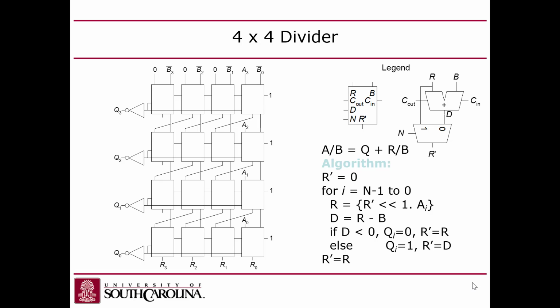Make sense? So that's the same thing I did here. When I subtracted this 3 from that 1, essentially the subtractor was only seeing the most significant bit of the dividend. You guys follow that? Right? These other bits were hidden, so the subtractor was just seeing a 1. So these boxes are actually full adders.